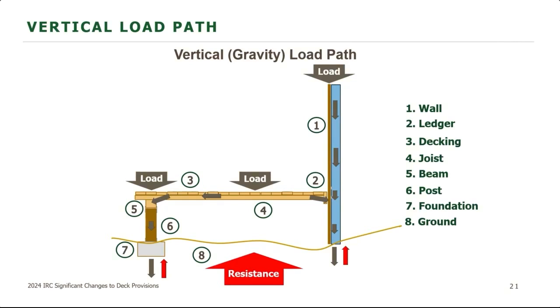That ledger board, though, and those ledger bolt connections are probably one of the most critical connections on the deck because it doesn't have anything directly underneath it, nothing directly to bear on. It's only being held on by those bolts. We'll talk about that connection later on.